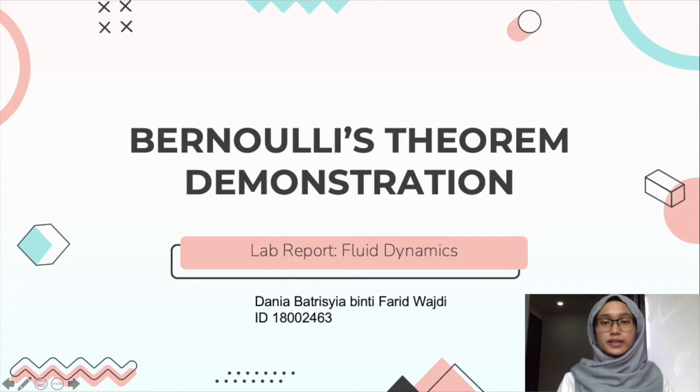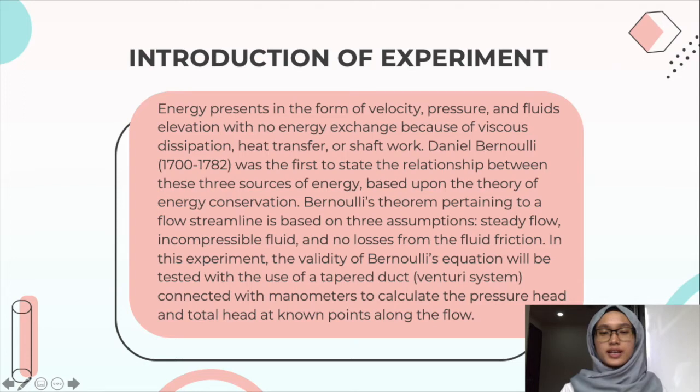For the lab report on fluid dynamics, I will present on the Bernoulli's theorem demonstration. For the introduction, energy exists in the form of pressure, velocity, and fluid elevation, with no energy exchange due to viscous dissipation, heat transfer, or shaft work. The relationship among these three forms of energy was first stated by Daniel Bernoulli, based upon the conservation of energy principle. Bernoulli's theorem related to a flow streamline is based on three assumptions: steady flow, incompressible fluid, and no fluid friction losses. The validity of Bernoulli's equation will be examined in this experiment.